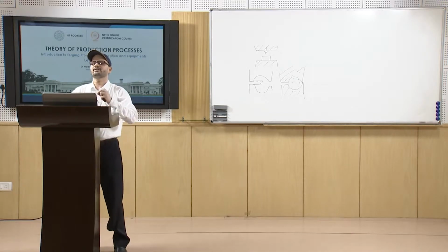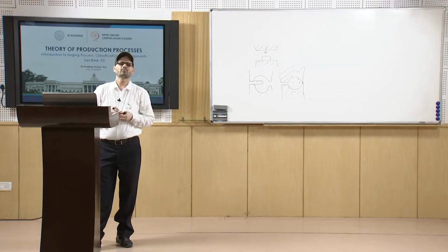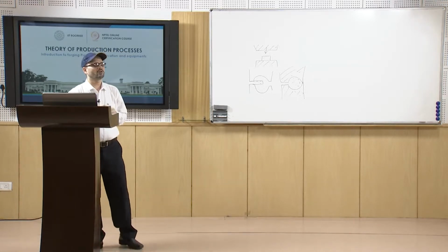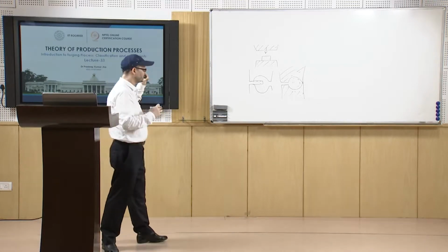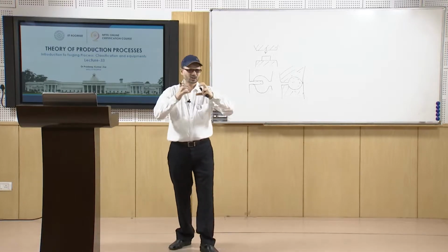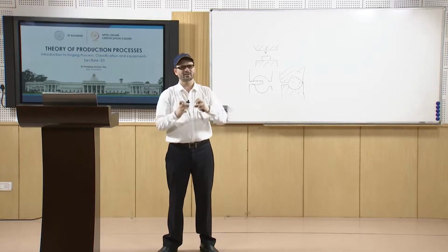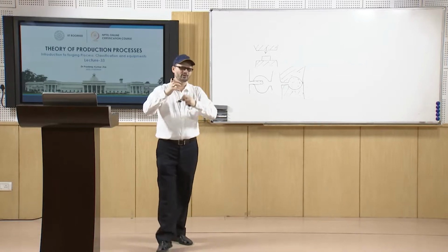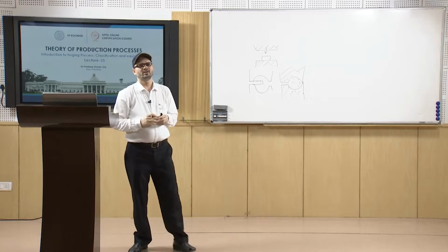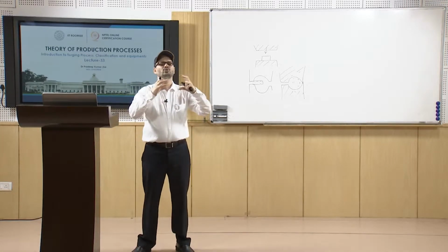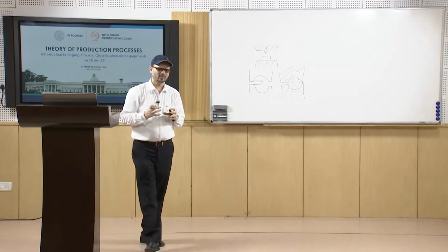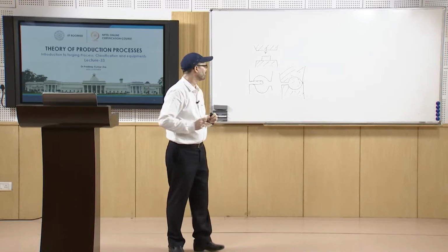You have a term known as fullering. Fullering means to reduce the cross section of a portion of the stock. When we try to do the forging at many places, you need to reduce the cross section. You have the fullering tool that we also used. You must have seen it in the smithy shops. Using that, wherever required, you can decrease the cross section.